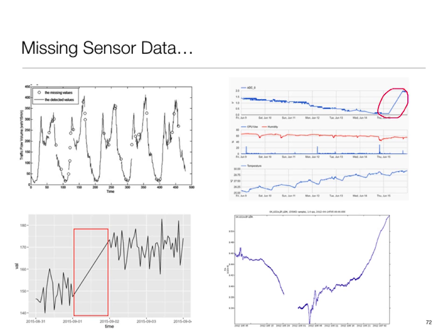So building on the redundancy theme, I may not have sensor redundancy, but I may have information redundancy. To give you an example, I talked about IMUs, accelerometer, gyro, and magnetometer. It turns out that you can compute the gyroscope signal from the accelerometer signal. Okay, so basically underlying. Okay, but it will be very much noisier. So it's lower quality, but you could. There are papers called virtual gyroscope, which are basically saying I can compute these things.